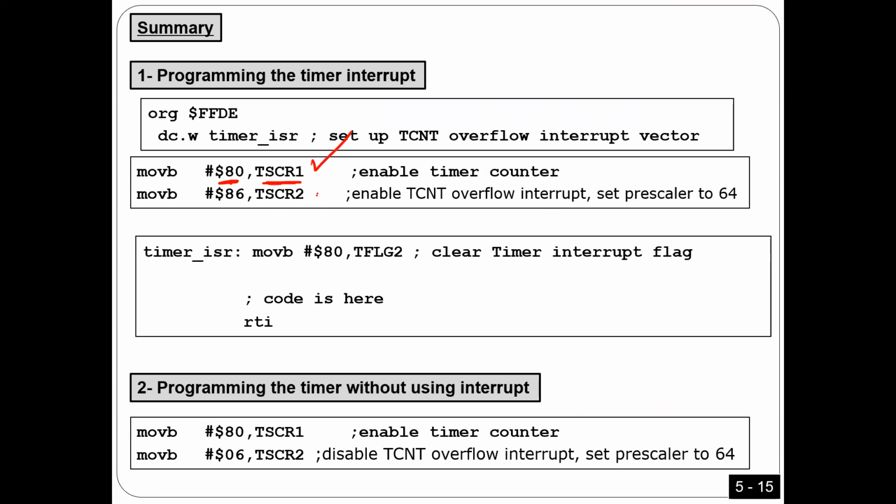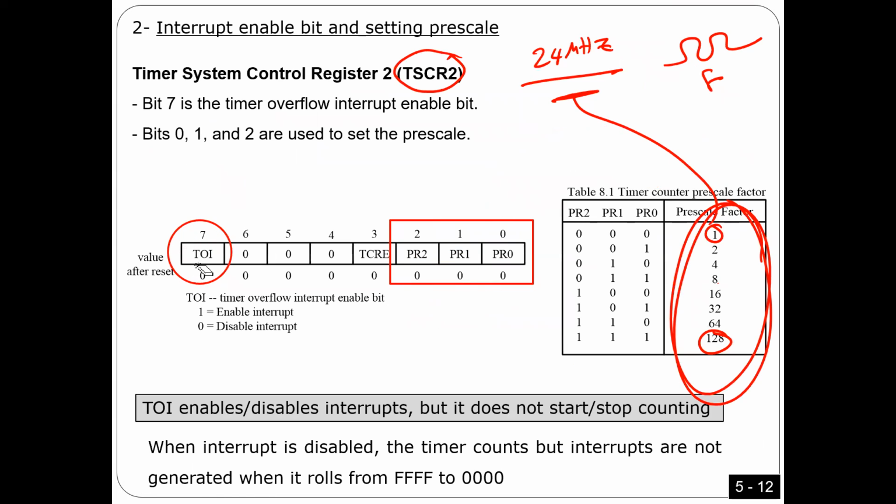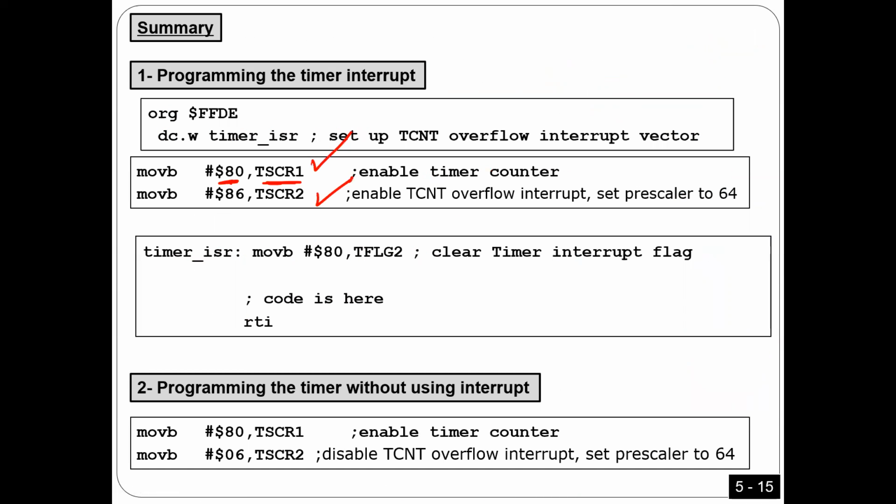We have another command, this register. Let me come here. Here, you have to put 1 for sure, to enable interrupts. And then you have to put a value here for this one. So again, only 2 until now, right? As you see here, guys, to do the configuration for the timer, you have to write some values to 2 registers in the main program. That's it. Once you do this, I'm done.